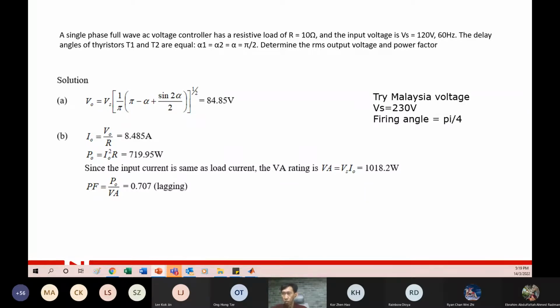But for motors you have to be very careful, especially AC motors. DC is still okay, but for AC motors, because of high harmonics, you get a poor power factor. Like I said, for LV, single phase is not a big issue, but for LV three phase, you will have a very serious power factor issue.